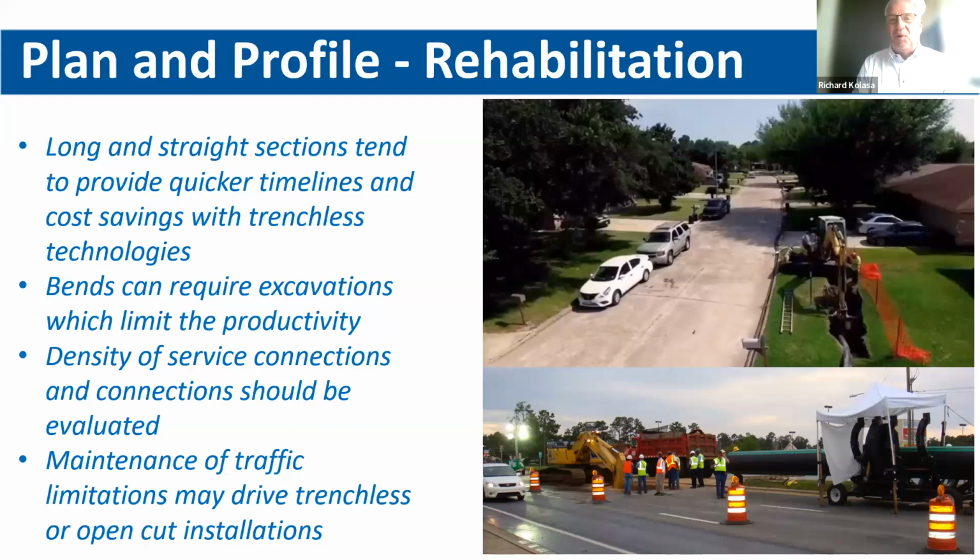And we have seen it before where they come back the next day, they've semi-grouted or sealed it, and that pipe is gone from the manhole because it's pulled far enough through, or they cut it off just to save themselves some time. So don't forget about that aspect of expansion and contraction, because it does occur in polyethylene.